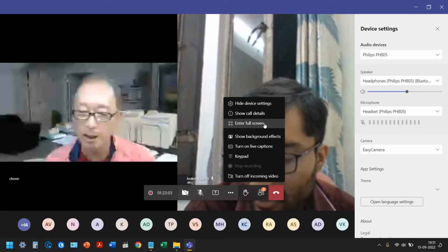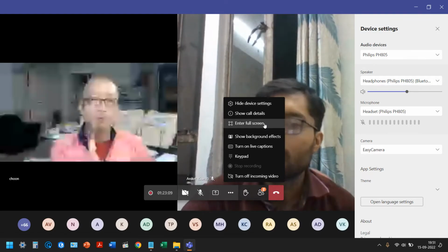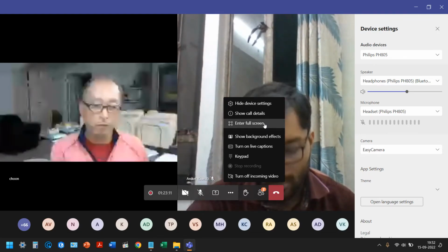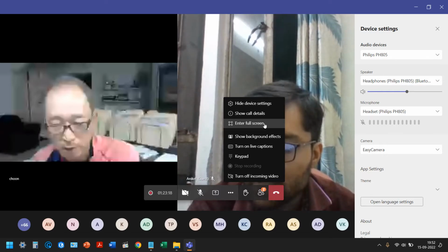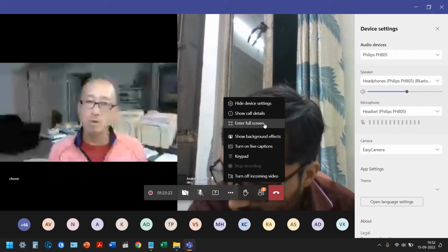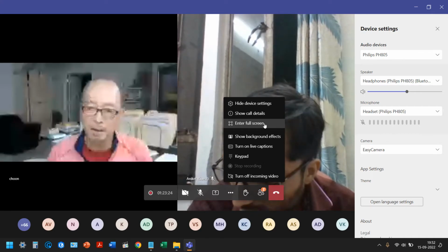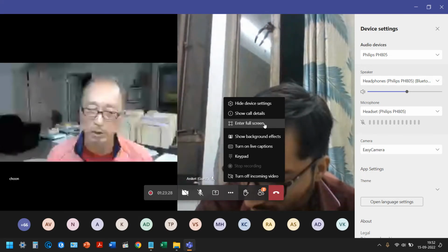And then the next question was the movement step, which is the survey interval. How much can you move after you collect one file? How much can you move everything to the next location? Usually it is 1 receiver spacing. So if you use a 1 meter receiver spacing, you move everything by 1 meter for the next measurement, which will give you the highest lateral resolution.